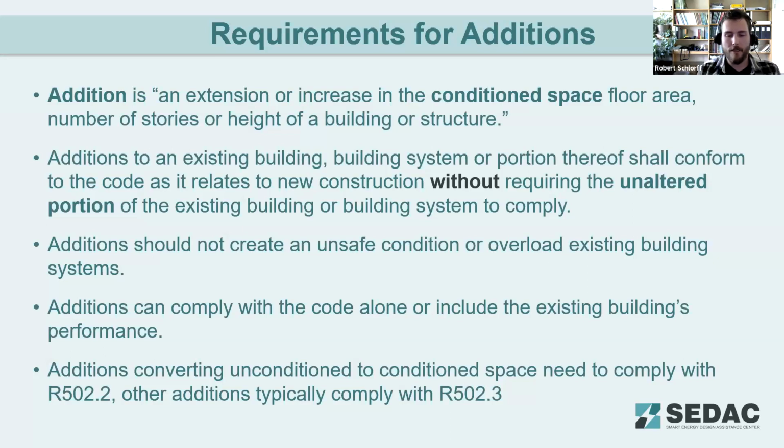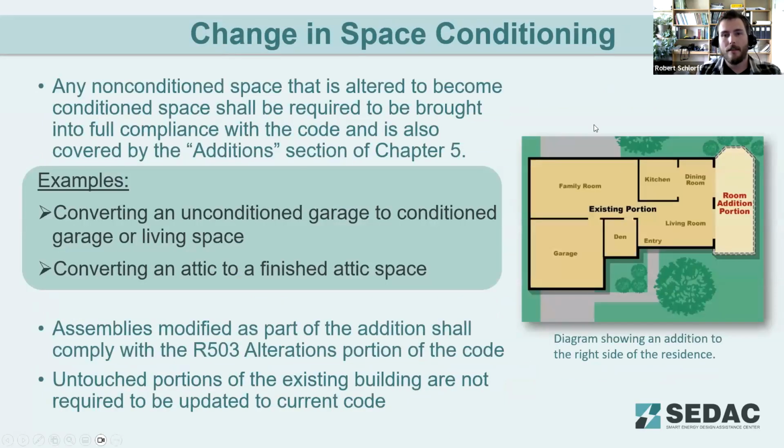We'll continue on and get a little further into that. The last point there: additions converting unconditioned space to conditioned space need to comply with 502.2. Other additions typically comply with 502.3, and we'll get to those in a minute.